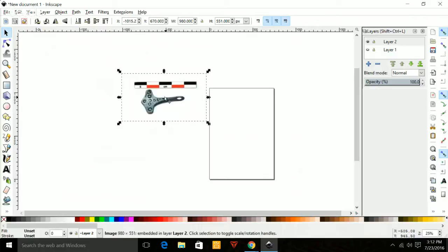I've actually looked at this ahead of time, and I've seen another picture of this particular Thor's hammer, and it tapers, so it's kind of a wedge with a circle at the top. So all I have to do is make a piece that is the same length as this original red piece that I've got, this one profile, and I've got a taper.